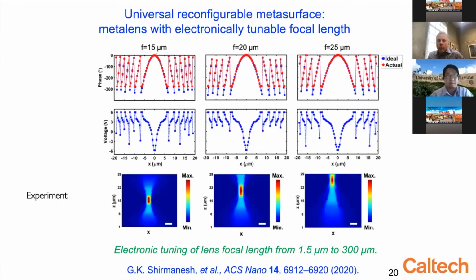In other words, if I were to focus a beam in the far field, I would have a focal length, and if I had perfect devices and perfect metasurface elements and could produce continuum phase gradients across the array, which I cannot do, then the ultimate limit to the focusing would be the diffraction limited size of the aperture.